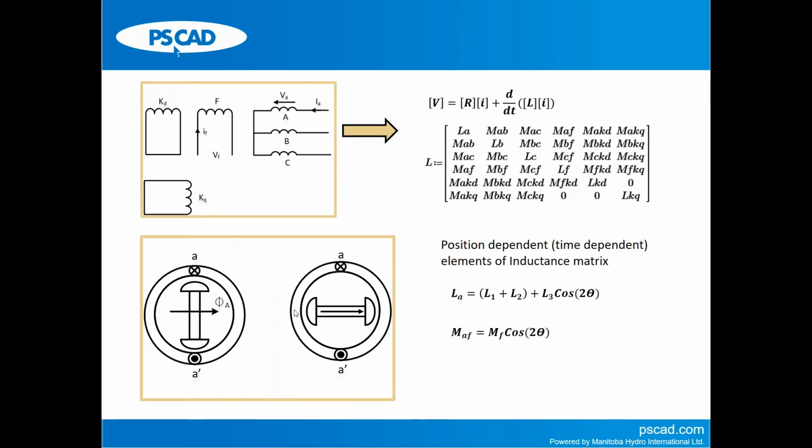the magnetic path provided by the rotor. So the reluctance seen by the flux is less in this case, whereas here, when the rotor is positioned like this, the flux has to cross a large air gap. So the reluctance, and correspondingly the inductance of phase A, is position dependent, is rotor position dependent.